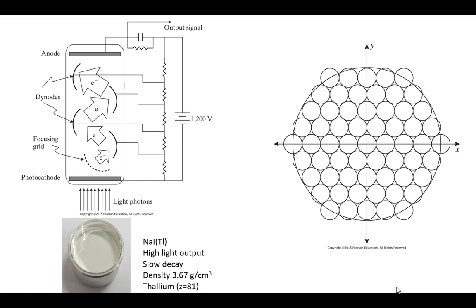If you've got cylinders, what are you doing? Oh, this is probably worth noticing. Remember I was saying the light and everything else? You will almost never see a practical one of these that you buy that doesn't have metal wrapped on the outside of it. And a big chunk of that is twofold. One is to prevent the light carrying out because it's completely opaque. The other one is you have electrons that are generated by these, and so you can ground those in between and prevent electrons going out from the other ones and causing nearby scintillators to act on.